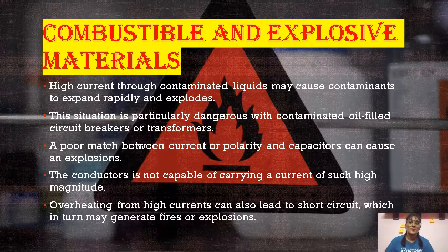Then I will explain about the combustible and explosive materials, where the high current through contaminated liquids may cause the contaminants to expand rapidly and can explode. This situation is particularly dangerous with contaminated oil-filled circuit breakers or transformers.